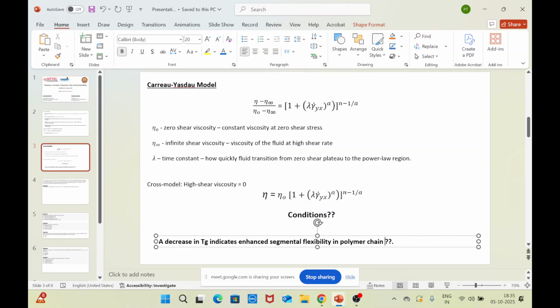It's going to be an inverse relationship, because the more the cross links, the swelling will be less. The more the cross links, the chains between the polymer chains between each of these cross links is going to be shorter. Shorter means the polymer chains are going to resist stretching more quickly, and since they resist stretching, the solvent molecules cannot come inside, so swelling ability decreases. So swelling will be less in those cases. So higher the density of cross-linking, lower will be the swelling ability.